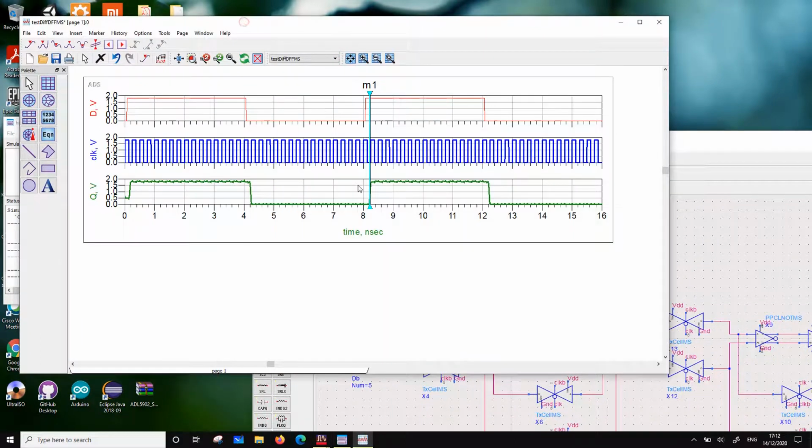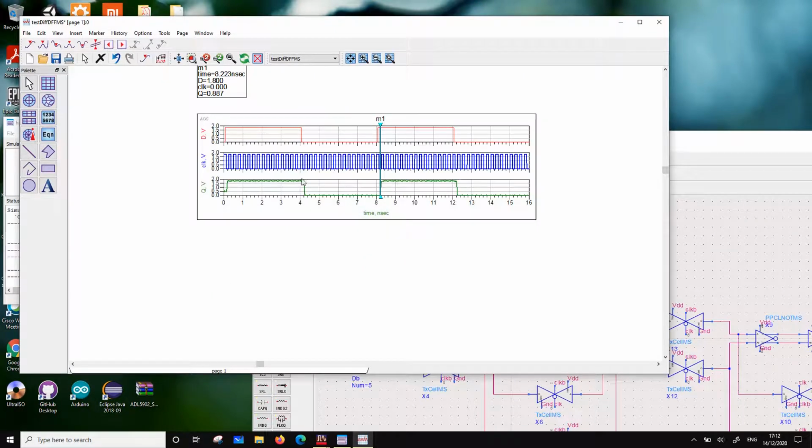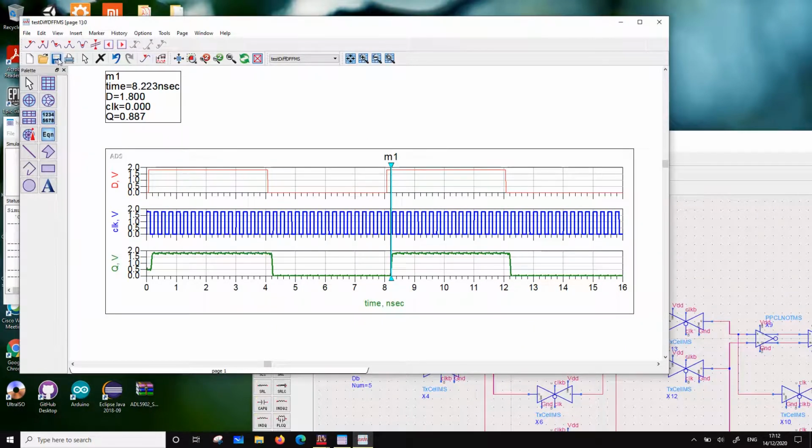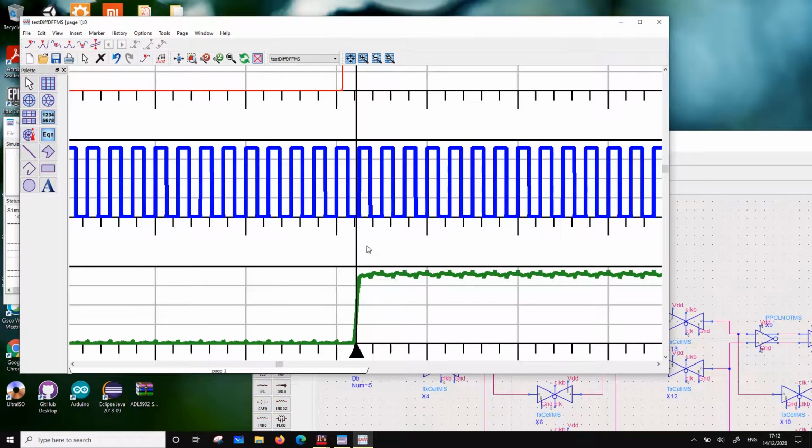Okay, so that's the delay what you are seeing, but this is going to be hazardous for a circuit. So you cannot operate this circuit at 4 gigahertz because you don't have a margin here. It's doing this transition on a positive, so there is a quarter cycle delay. So maximum frequency cannot be 4 gigahertz in a larger circuit, though for demonstration purpose it's okay, right? Because there is something called a setup time here, right?